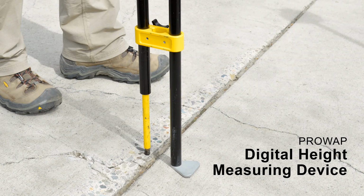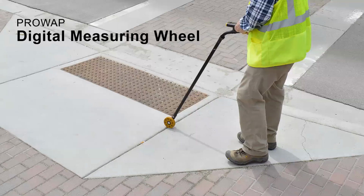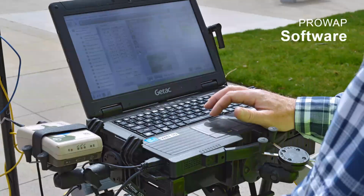The digital height measuring device measures vertical transitions and horizontal opening depth, while the digital measuring wheel quickly collects short distance dimensional measurements for elements such as curb ramps or sidewalk widths. The cart also includes a laptop with the ProApp software, which was developed by Beneficial Designs for the assessment of the public right-of-way environment. With the stroke of a key, the software is designed to work with other ProApp tools by monitoring and capturing live values such as slopes and lengths.